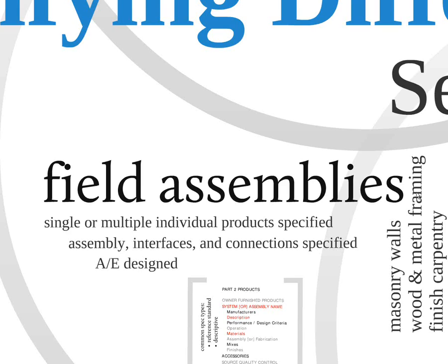Whereas in the preceding category, the curtain wall is basically a single source responsibility, and so in the majority of your buildings primarily clad in curtain wall, there's a single entity, manufacturer, that takes responsibility for performance of that entire wall system.